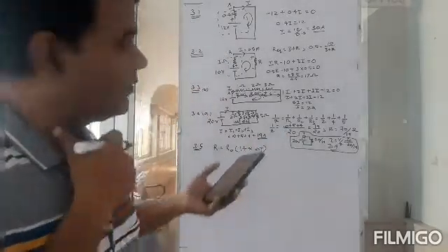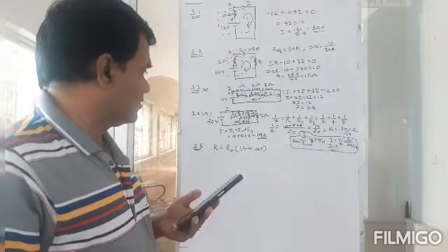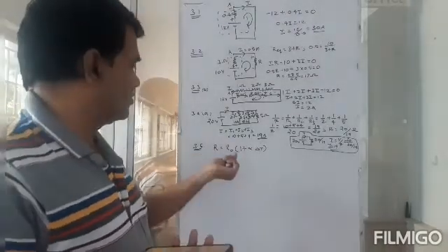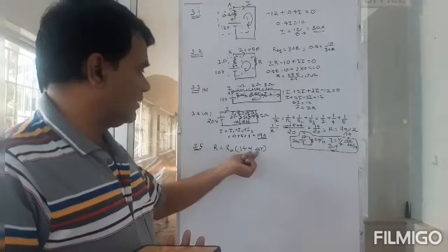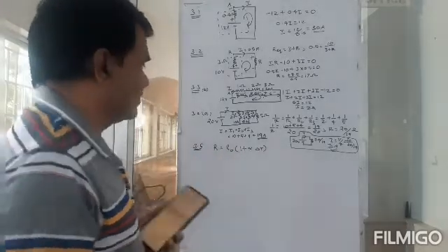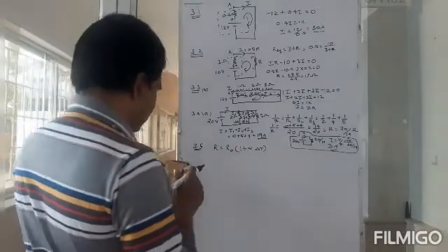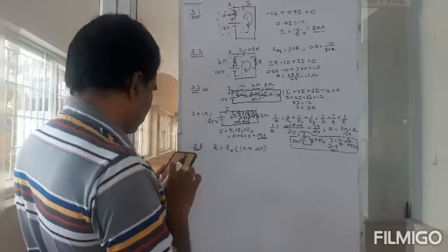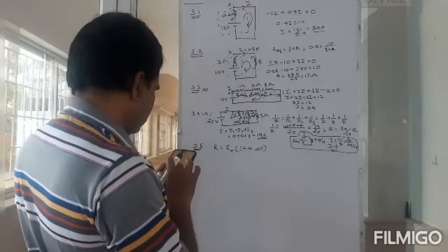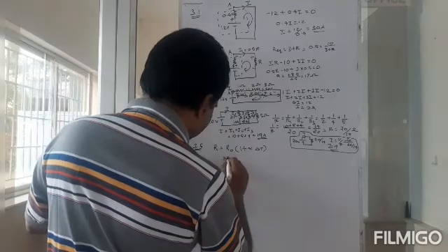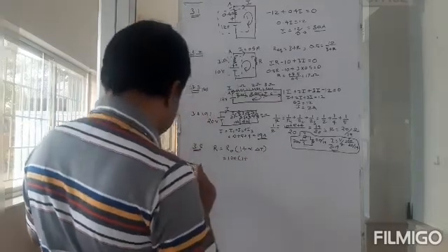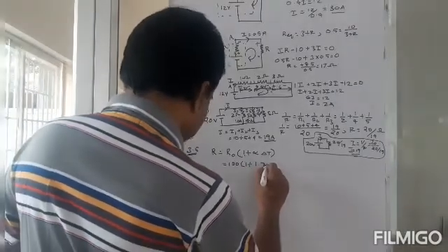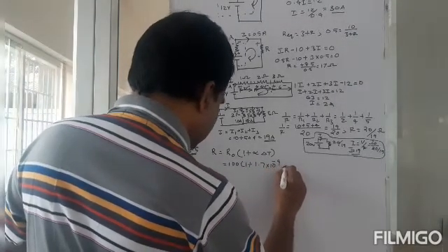This is the expression we have come across in that lesson. So R0 is the original resistance or the reference resistance, and then this is a new resistance. Then alpha is given. So all that you need to do is to find delta T, right? So okay, what is given? What is R and R0? Room temperature, this is 100. 1 plus, what is alpha? Alpha is 1.7 into 10 to the power minus 4. Delta T you don't know.